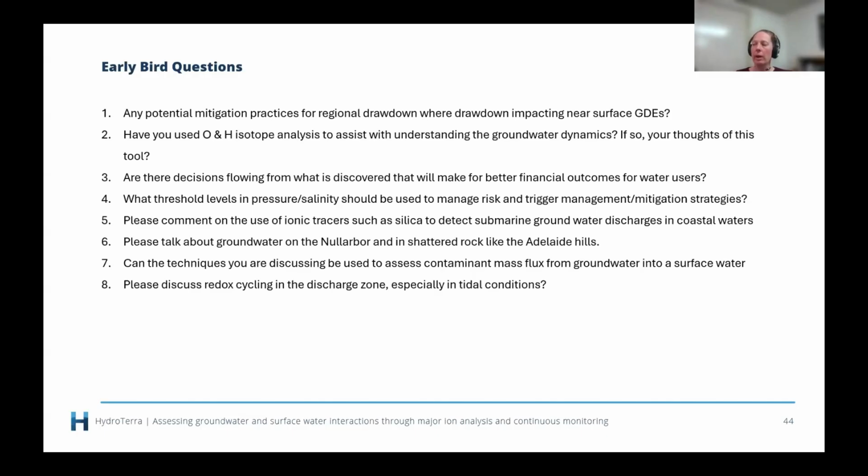So an example that I was thinking about is a site I work on where they have an automated monitoring system that measures salinity and turbidity in a sump, basically, and they can only discharge below a certain trigger value for both of those parameters. And they've got sluice gates that open when that monitoring says the water quality is okay to discharge to the nearby creek, and then they close when the water quality exceeds the limits. So that I really can't talk to too much more detail because that's really a site-specific question in terms of your specific contaminants and COPCs and the risk and the receptors that you're dealing with, but just a few things to have a think about there.